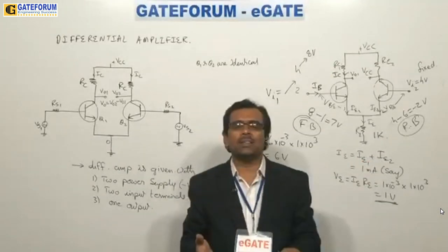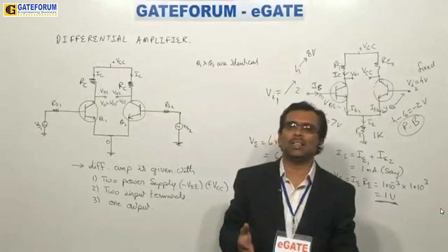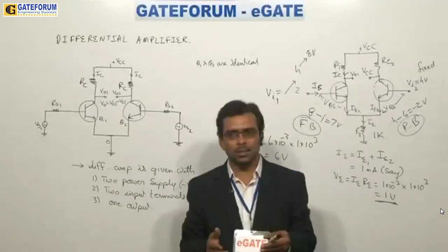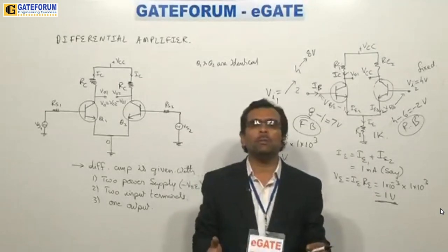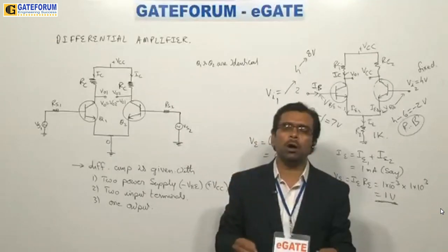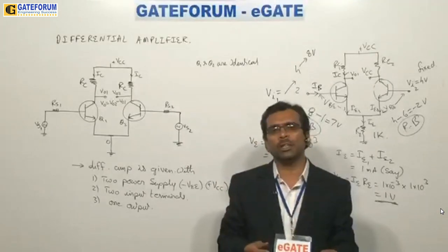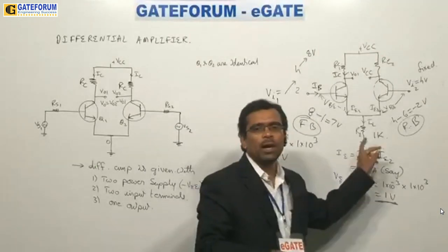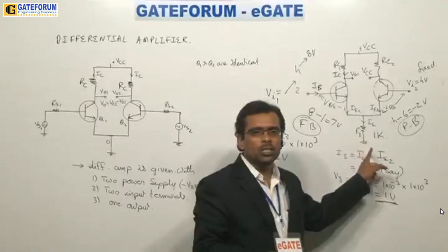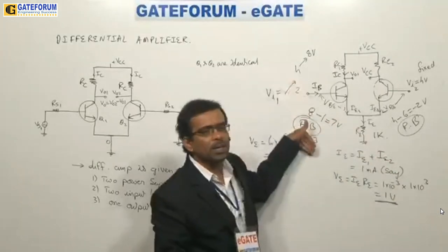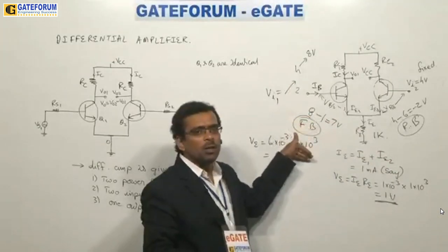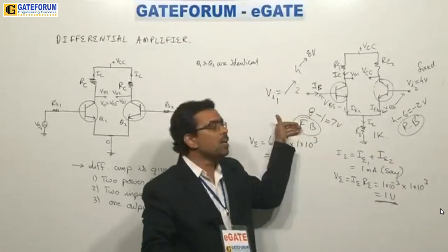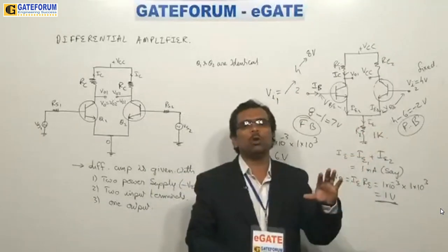Because of that reason, you should operate the op amp within a limited region. Then that becomes a difficult task. Why? Because I have a wide range of input signals when I want to give them to the op amp and get the signals processed. So the only option we have is that these transistors must be controlled such that, all of you listen carefully, even though my input signal varies, the swing increases and decreases to a great extent, these transistors must not go to cutoff.